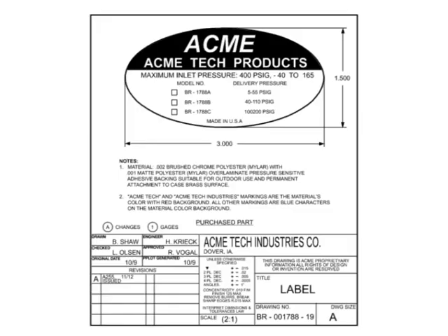Another type of detail drawing is the purchase part or procurement drawing. This type of drawing details all the information required to buy a stock part off the shelf. This type of detail drawing typically only shows information useful to the purchaser to detail the performance or configuration of the item required. These characteristics are typically called the form, fit, and function of the part. It's up to the manufacturer to develop detail machine or casting drawings that conform to the purchase part drawing requirements.